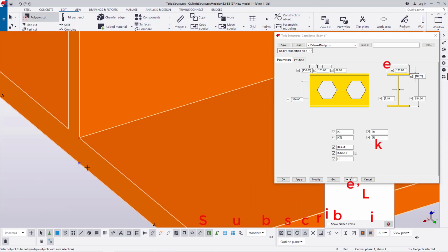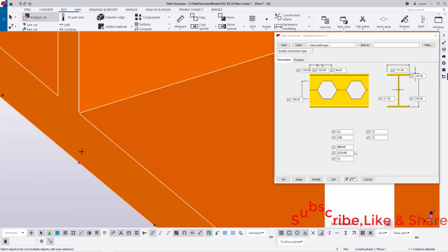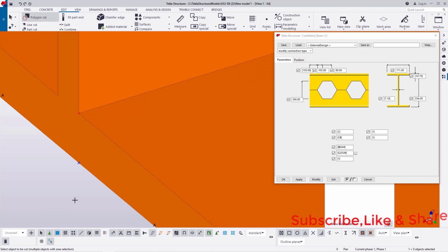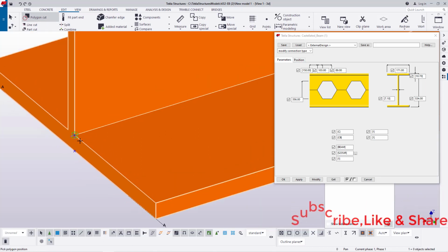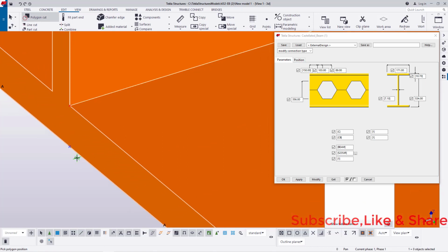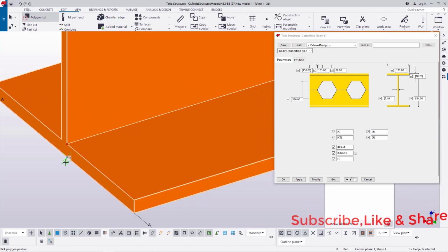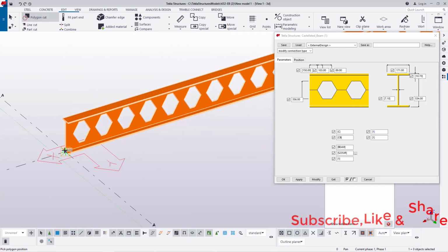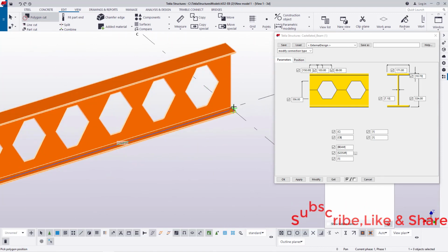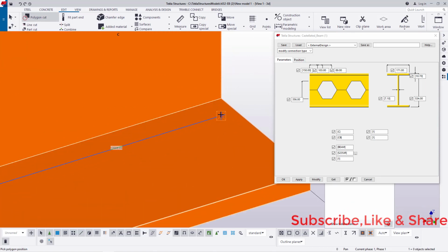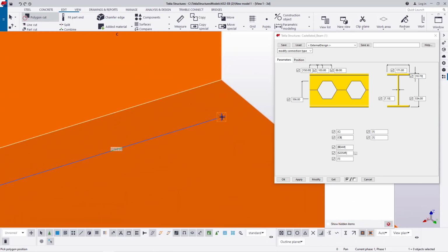The polygon cut is what we are defining. The moment you invoke that command, you'll see that at the bottom end here you're being requested to pick the object to be cut. I'll pick this object to be cut, then I'll start defining my polygon, and I'll start from that spot, and I'll move all the way to the other end. You can move from any direction as long as you close down your path. Your path is closed to define the path to be cut out.